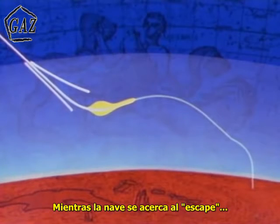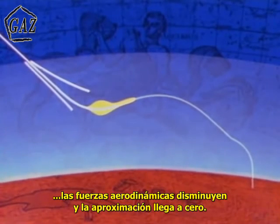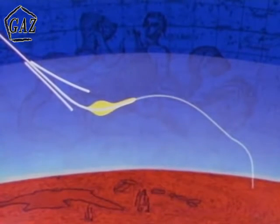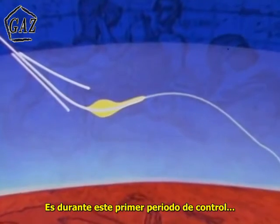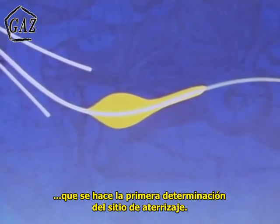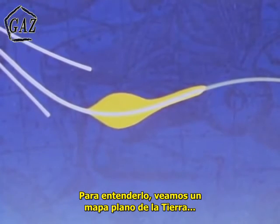As the spacecraft approaches the skip, the aerodynamic forces become less and approach zero, so aerodynamic control approaches zero. It is during this first control period that the real determination of where the spacecraft will land is made. To understand this, let's take a look at a flat map of the Earth.